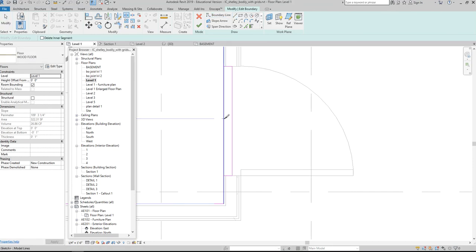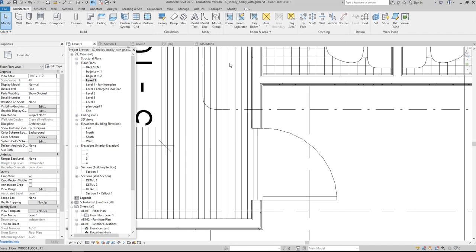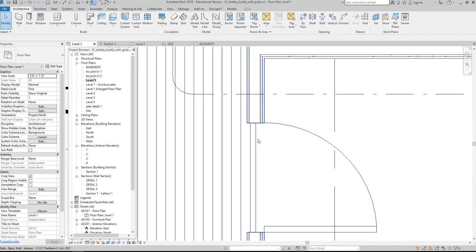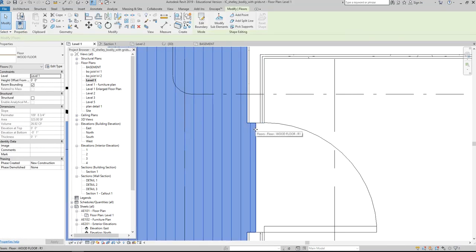I'm going to split that line right there and then trim it, TR, like that. It just depends on really how your flooring is running, right? You could have your flooring running and stopping, and then this flooring goes into the door, or you could do halvesies, right? So I've got half my floor running to where the threshold is going to cover, right, where the door swings, because if the door swings shut, it will cover that, and then the other floor will be outlined and come into there and just meet it. Yeah, that's a good question.